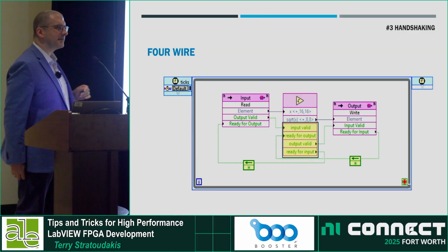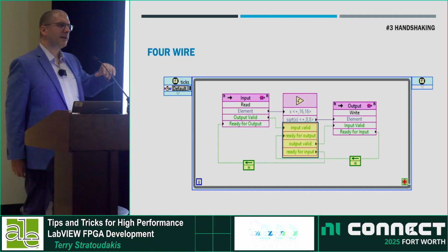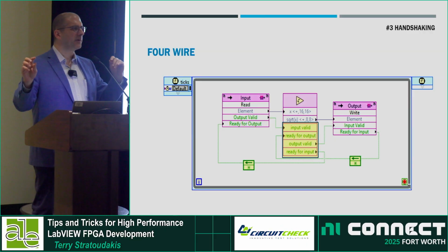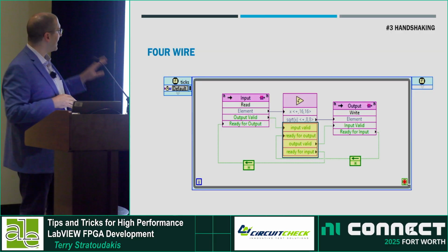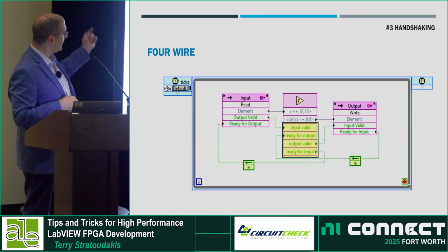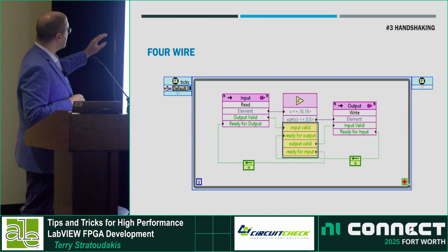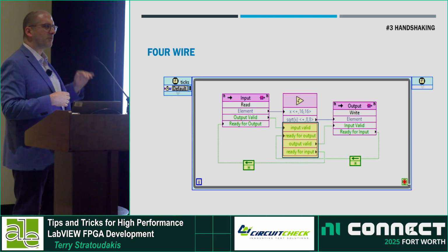4-wire handshaking is we have the function in the middle. That's a square root function, and that function has an input and an output. Because it has an input and an output, we now have to manage handshaking from both sides. We have to handle handshaking from the input function, FIFO, and from the output. And I know that sometimes these handshaking can get really busy. My advice is to just take them one step at a time.